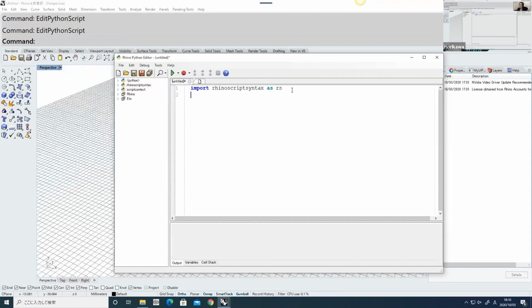And there's also a bit lower-level API called Rhino. This is the Rhino Common SDK. It's a bit different from rhinoscriptsyntax. Rhinoscriptsyntax is kind of a utilized scripting module, which depends on the Rhino Common SDK. So I think in most cases, it's okay to use rhinoscriptsyntax at the first line, but sometimes if you need more low-level operations, you also need the Rhino Common SDK as well.